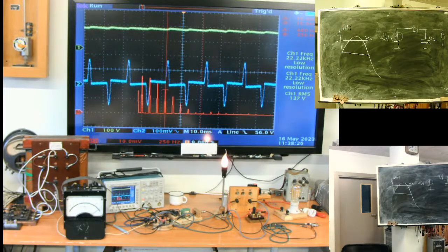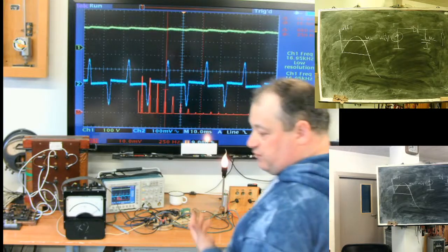The fifth harmonic is closed by windings of hydro generators. If you have, for example, an island with only solar and wind power, you will have no path for the fifth harmonic to close in a generator, because inverters of photovoltaics and inverters of wind generators do not pass the fifth harmonic through them. And you will see corrupted voltage.